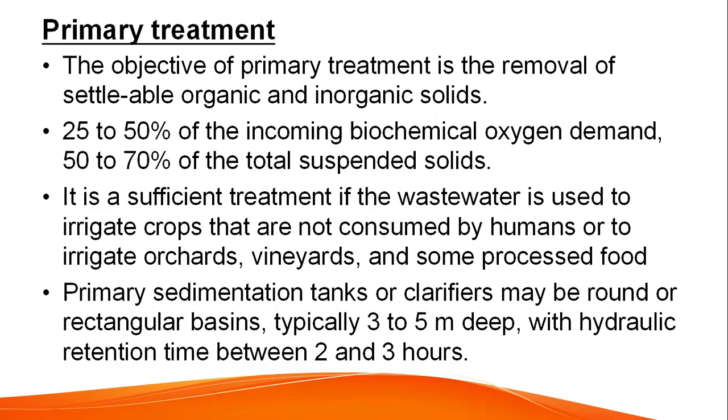It is a sufficient treatment if the wastewater is used to irrigate crops that are not to be consumed by humans, or certain crops which are to be fed to animals. If they are not to be consumed by animals, this process is totally fine. This treatment is totally feasible. Or to irrigate orchards, vineyards, and sub-processed food.